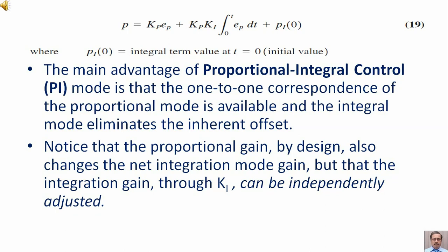Notice that the proportional gain by design also changes the net integration mode gain, but that the integration gain through k subscript I can be independently adjusted.